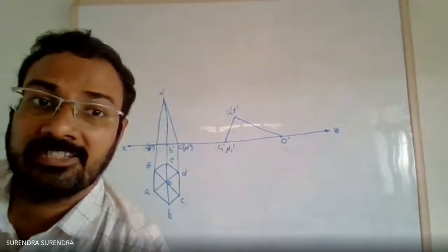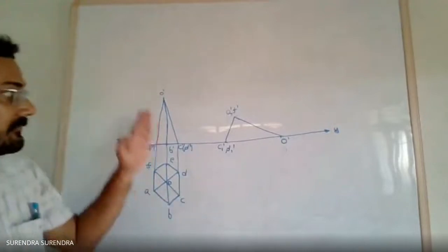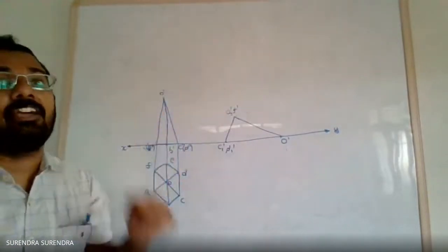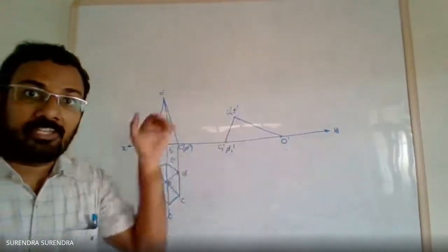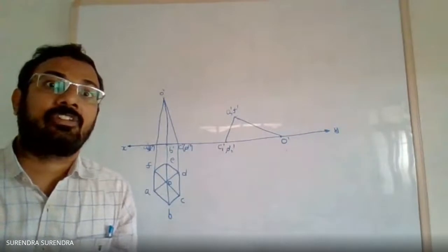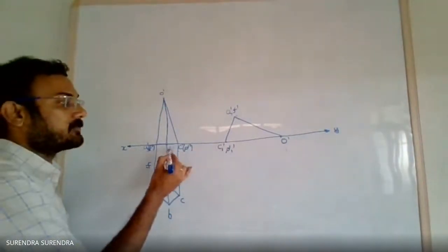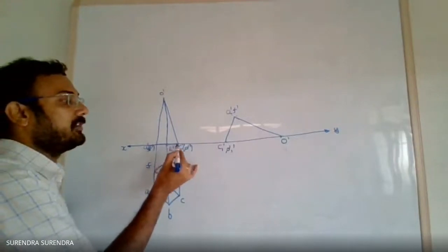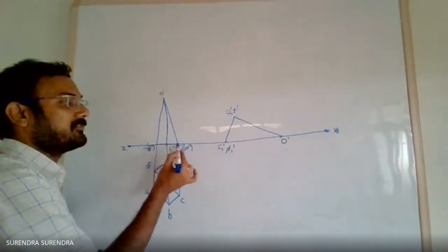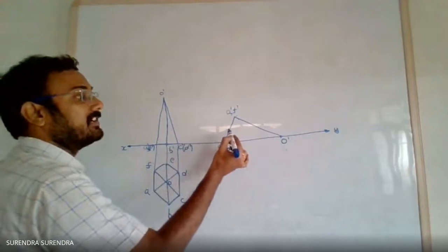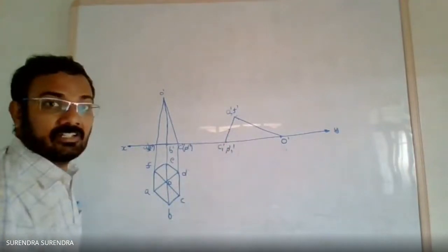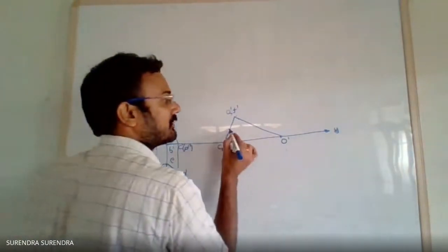Now we got the same pyramid in lying position, lying on one of its triangular faces on the ground. For getting the B dash point, measure the distance from D to B. With D as center, draw an arc. Also join.